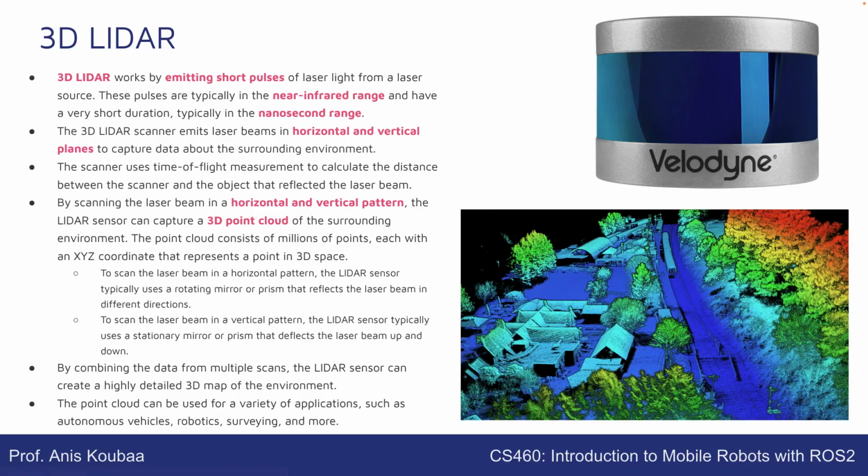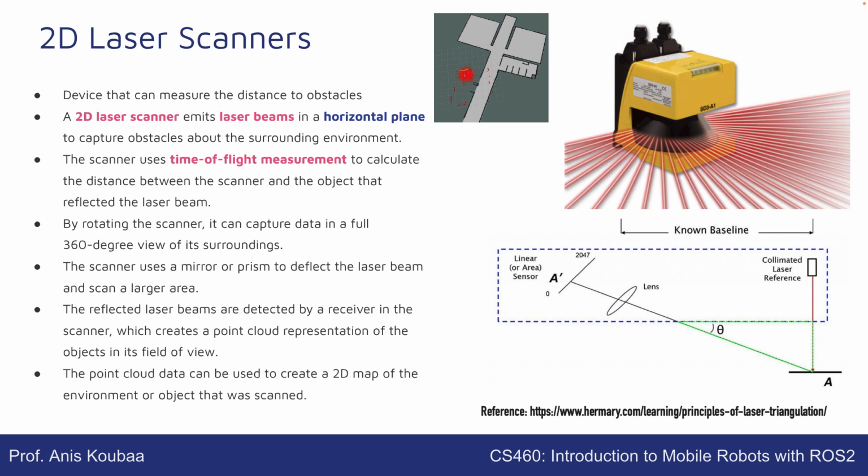When we detect obstacles, there are some algorithms called SLAM that allow you to build a map. Look, for example, here, this map is something that you can build with a robot using a laser scanner. You will see we have free space here, and obstacles here. These obstacles are detected by the laser, and then they will be fused by the SLAM algorithm. This laser reading will be fused with other readings, like odometry or other types of sensors, in order to decide which places in the environment are free and which correspond to an obstacle.